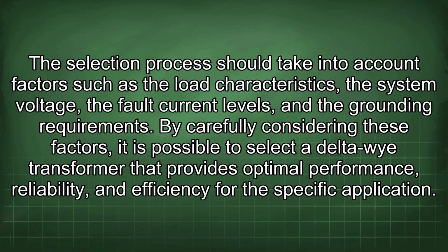The selection process should take into account factors such as the load characteristics, the system voltage, the fault current levels, and the grounding requirements. By carefully considering these factors, it is possible to select a Delta-Wye transformer that provides optimal performance, reliability, and efficiency for the specific application.